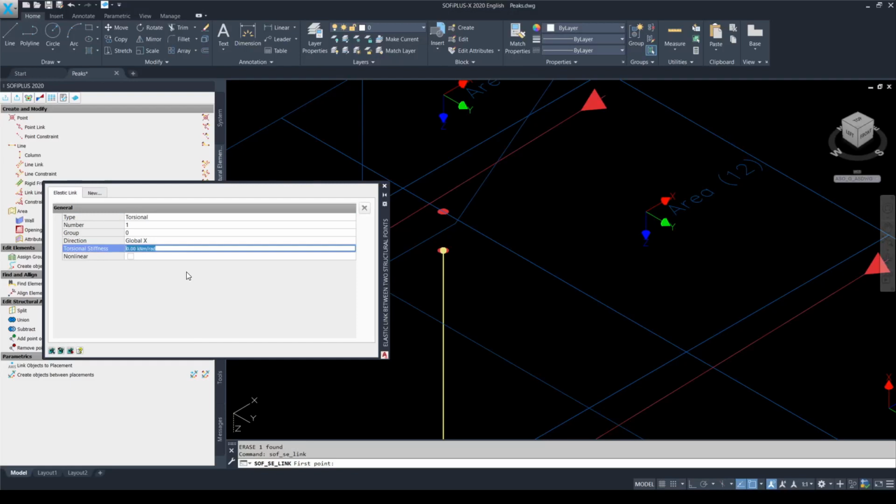The stiffness of the axial and the torsional springs needs to be chosen carefully. If they are given with a too high stiffness value, then again this location will attract a lot of bending moment. However, if they are too weak, then it might lead to instability of your structure. So you really need to play with the stiffness value of the springs to find a reasonable solution to be able to get rid of the high peak values in the bending moment, but on the other hand also keep the deflections in a normal range.